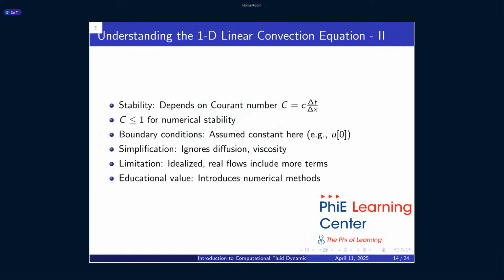So moving on. This is what I said earlier. We have the CFL number, and the CFL number has to be less than 1 for stability. The stability analysis will be covered by Sanjay in the forthcoming sessions. Now the simplification that we do here is we didn't consider the non-linear term, that u dou u by dou x on the right hand side of the Navier-Stokes equation. When we consider it, we have to use the appropriate schemes properly. So we look into Lax-Wendroff schemes and other stuff.